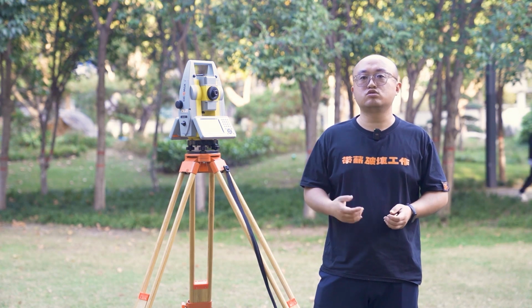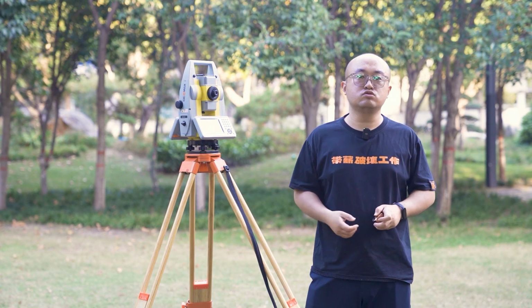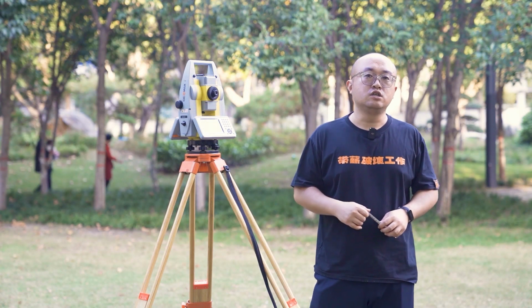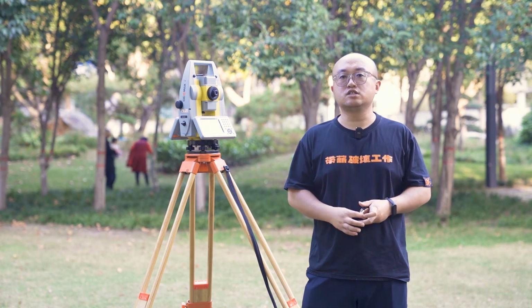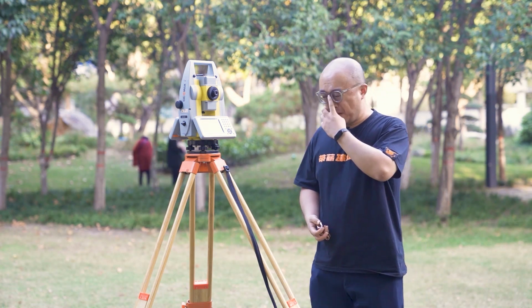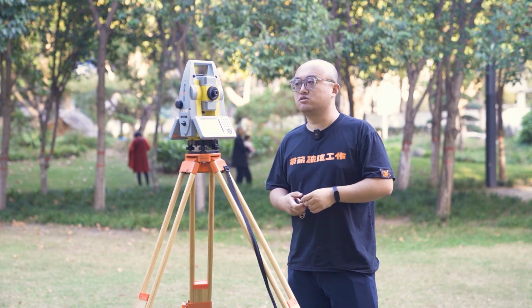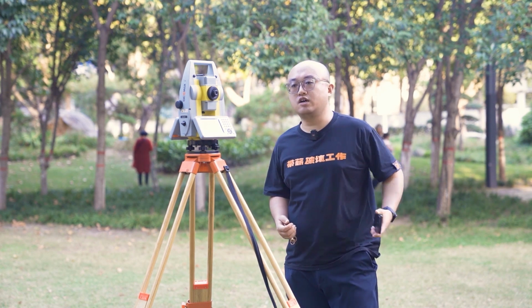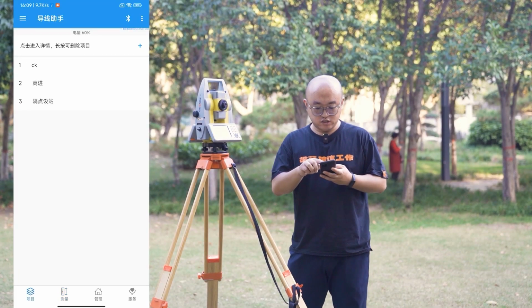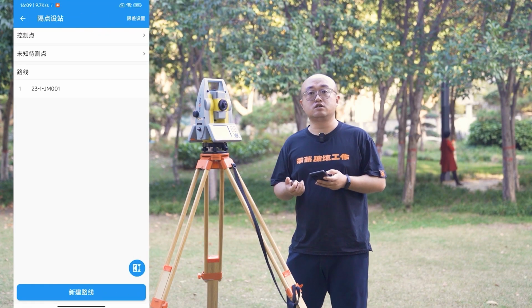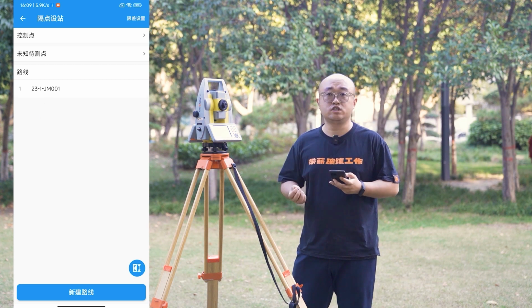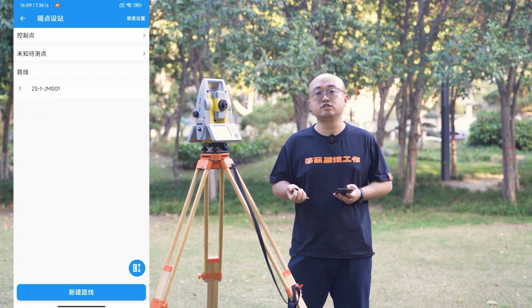We placed it on the ground, but during actual observation, I suggest that you use fixed height equipment to place prisms, such as centering rods, whose height is fixed. Because errors such as prism height or instrument height can directly affect the final result of trigonometric elevation. We will now set up the instrument at a location where we can view both control points, and then open our software. On the software, I have already created an elevation traverse project and a route in advance.